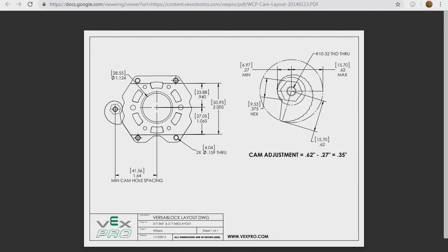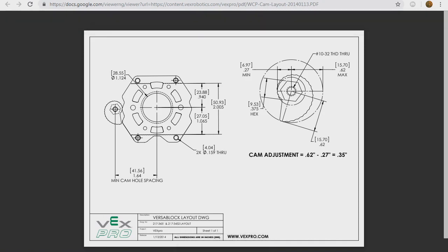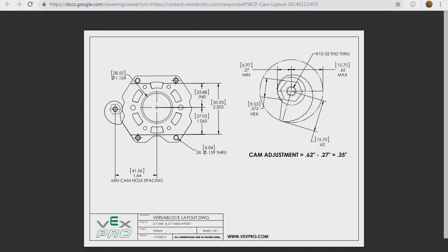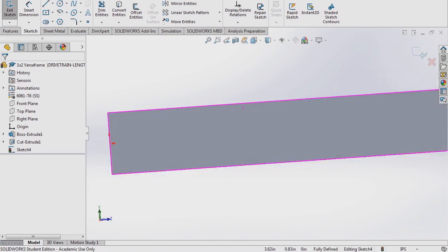And that's because you can use this piece for a drop center, like you have the outer wheels with the flat top of the block, and then your center wheel can be the dog ears, is what we call them on SWAT, the dog ears on the top, to give it a drop center. And I think that's like a 16th, maybe an 8th of an inch drop. But yeah, we're actually not going to use that, but we are going to be using the flat edge on top, so we're going to be using the 0.94 inches from the top for our outer slots.